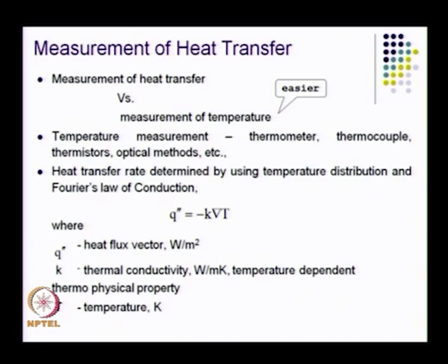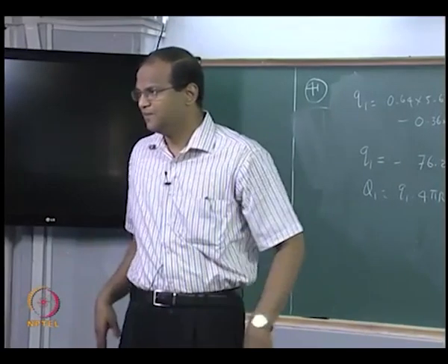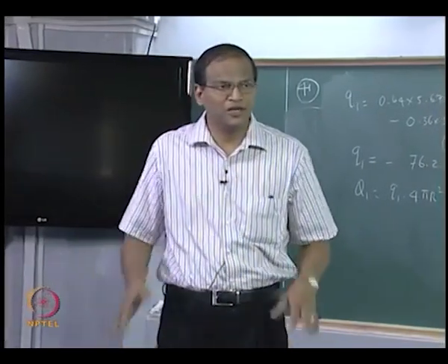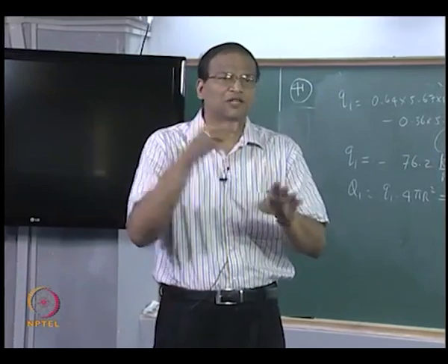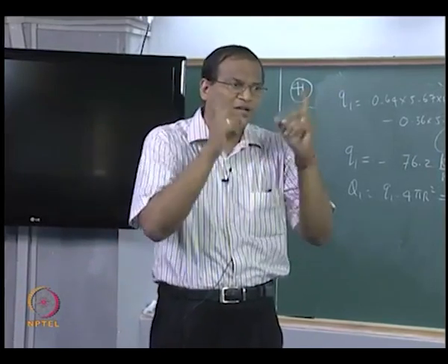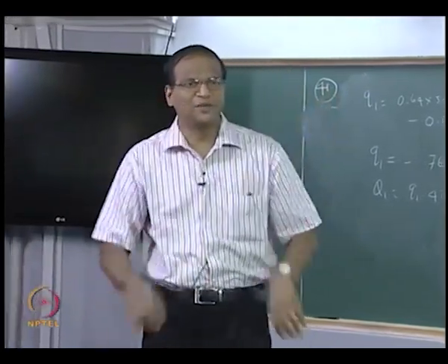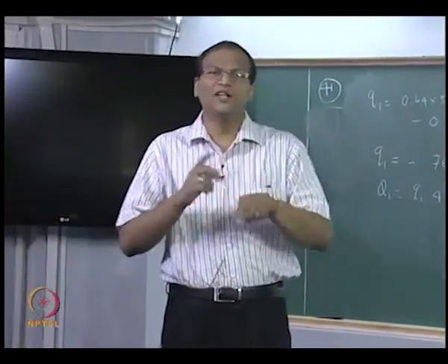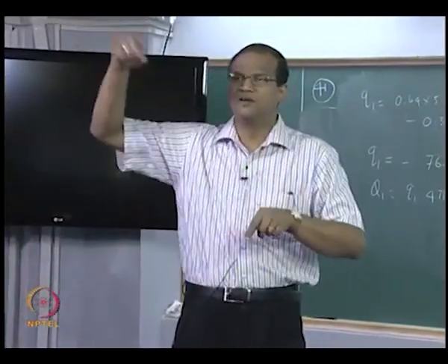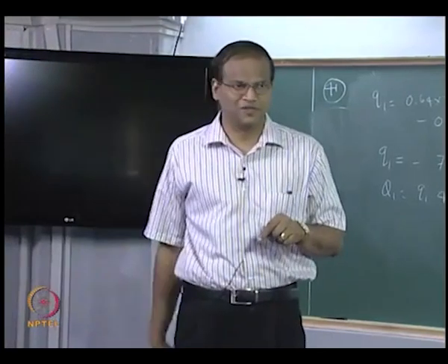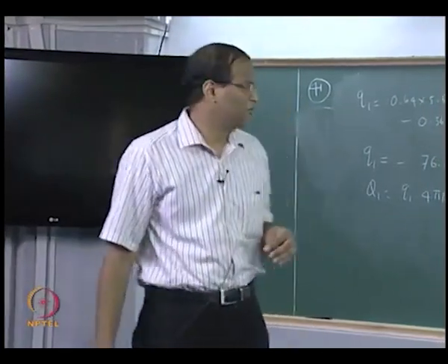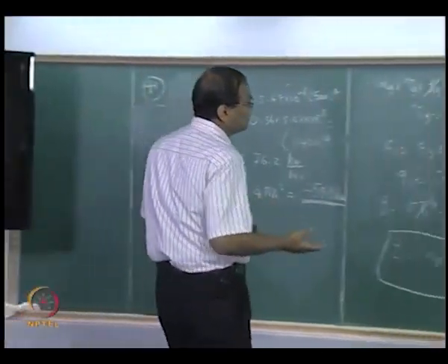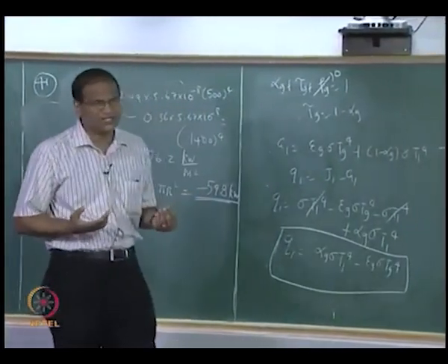In liquid crystal thermography, you have a sheet and paste it on the surface whose temperature is changing, where there is a temperature distribution. The color of the sheet will change depending on the temperature. Then you take a picture with a high speed camera or a CCD camera, convert the colors to temperatures, and then you get the temperature field. From that you solve additional equations, you solve inverse problems and so on. That is liquid crystal thermography, right. So temperature is a lot easier to measure.